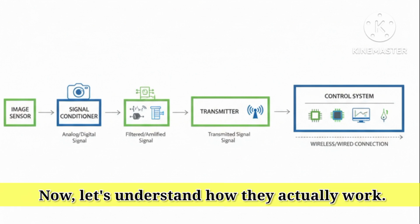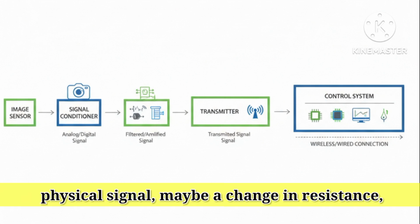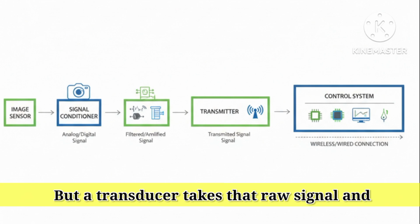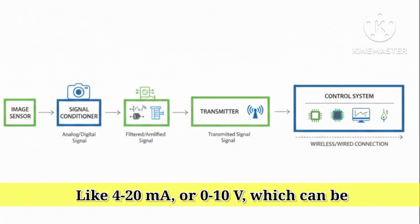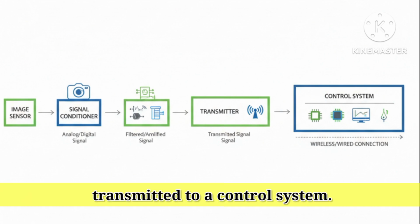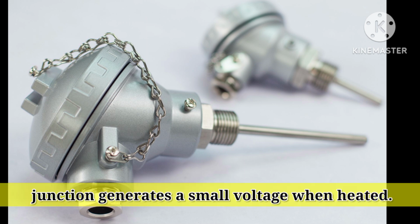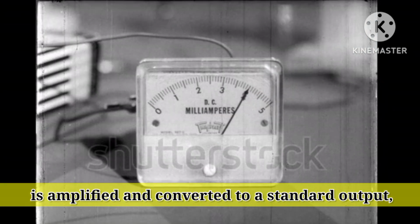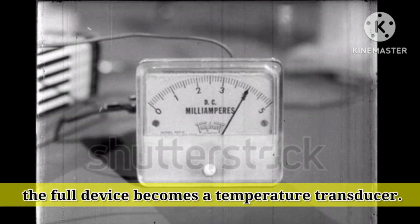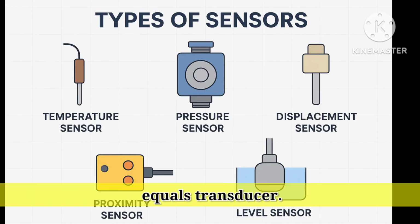3. Working principle. Now, let's understand how they actually work. When a sensor detects a change, it outputs a raw physical signal, maybe a change in resistance, capacitance, or voltage. But a transducer takes that raw signal and converts it into a standard format, like 4 to 20 milliamps, or 0 to 10 volts, which can be transmitted to a control system. For example, in a thermocouple, the sensor junction generates a small voltage when heated. That's the sensor part, but when that voltage is amplified and converted to a standard output, the full device becomes a temperature transducer. So we can say, sensor plus signal conditioning equals transducer.